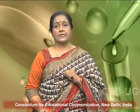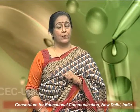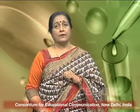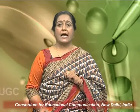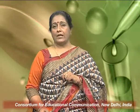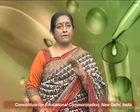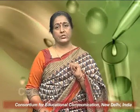In the United States, another unit of viscosity known as Saybolt universal viscosity is frequently employed in the petroleum industry. It is expressed as the number of seconds required for 60 cc of the oil to run through a standard orifice from a cylinder filled with a definite volume at a standard temperature.